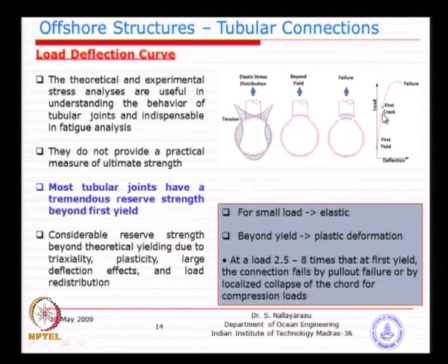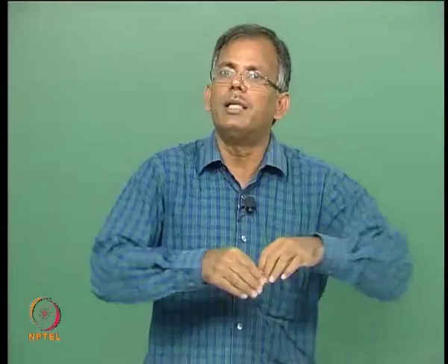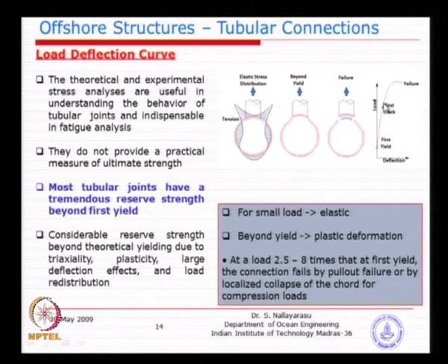Very similar to the discussion we had on the plastic collapse analysis, basically you keep on increasing the load until such time the hot spots start increasing from one location to multiple locations. Basically one location yields, load is transferred to the next point and the next point, and the next point. So, you will see that basically cracking will happen after a sufficient amount of load has been applied, but one small crack does not fail.